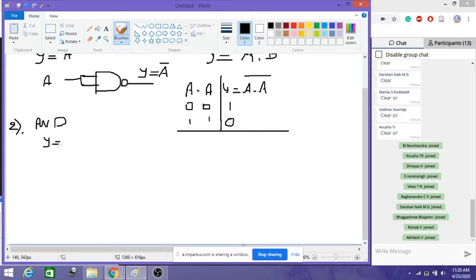The equation of the AND gate is A into B. How do we get this A into B? To get A into B, we are going to apply the involution law. That means just apply this double bar, because the double bar results in the same thing, that is A into B itself. It doesn't affect much, but it will help in simplifying into a NAND gate. If you look at just this term with a single bar, it is in a NAND gate form.